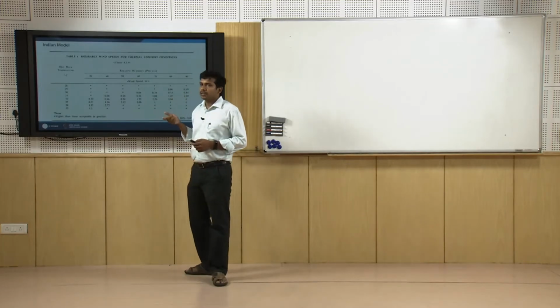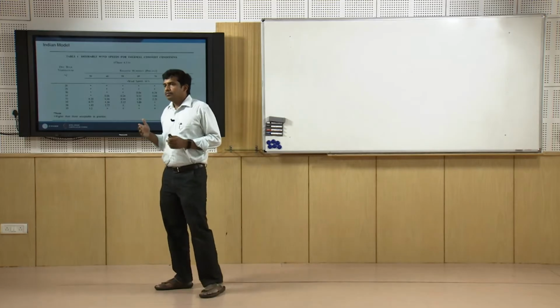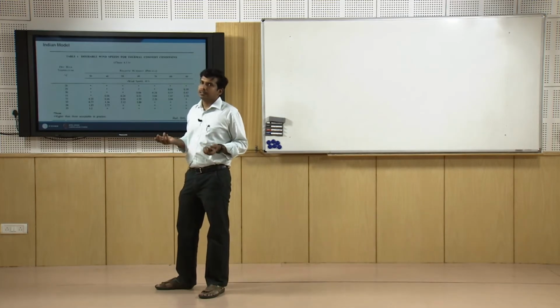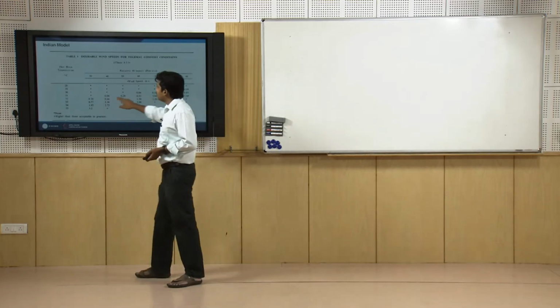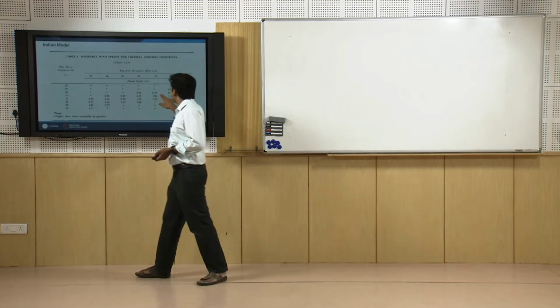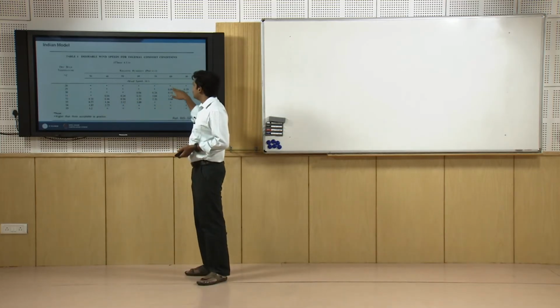Looking back at our measurement, we said a well cross ventilated residential space gives around 0.4 to 0.5 meter per second, which means at 30 degrees, up to 80% humidity you will still be comfortable, and marginally comfortable even at 90% relative humidity.